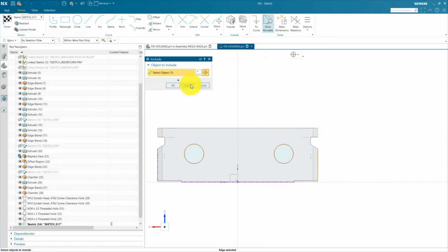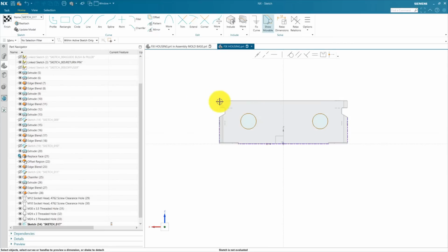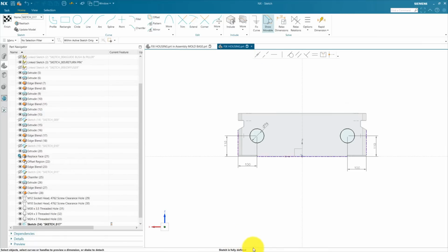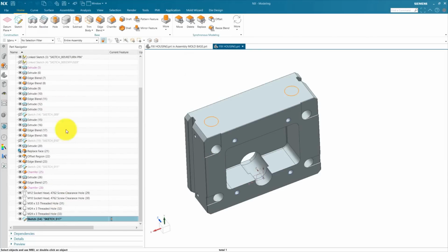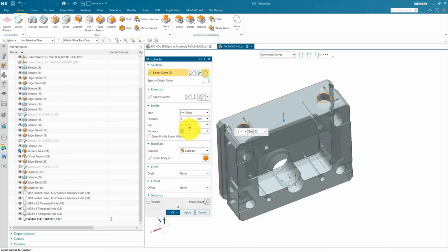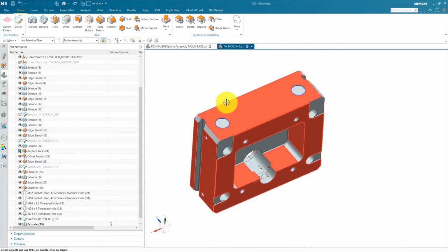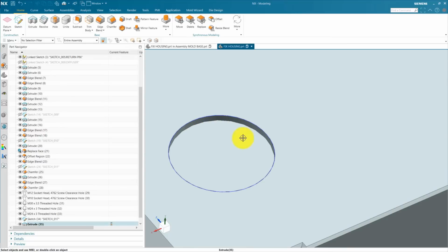At this point we are going to define both circle positions individually. Our sketch is fully defined. Finish this sketch and extrude it 5 mm, press OK. Add a bolting hole inside the center of this.